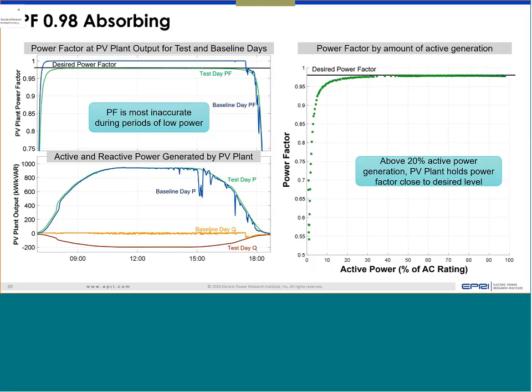Another question: as one can see on slide 20, the slide that is showing right now, the reactive power is non-zero while maintaining unity power factor. How close to zero is close enough? That's a good question. When you ask it to operate at unity power factor, we have seen power factor like 0.997, 0.998. Occasionally, it can go up and down, and that depends on a lot of cases.